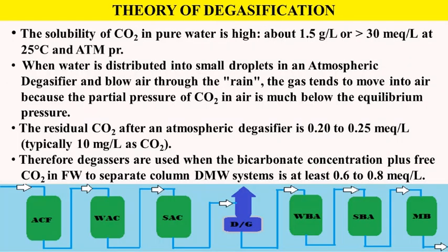In the degasifier, the solubility of carbon dioxide in pure water is high, greater than 30 milliequivalent per liter at 25 degrees centigrade and at atmospheric pressure.